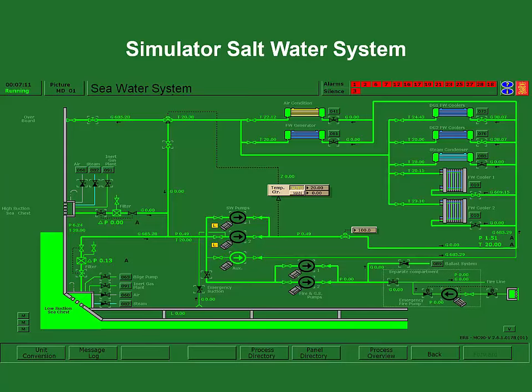And then on the Kongsberg, you can actually see the green around the hull. That is the depiction of the saltwater level outside the hull. And so you realize that if you were to switch over to the high suction, you would actually draw in air instead of water. Okay, so this is your low suction, and this is your strainer. You have 3 pumps. 2 large pumps, your main saltwater pumps, which are powered from the main switchboard, and a much smaller auxiliary or harbor pump that is driven off the emergency.